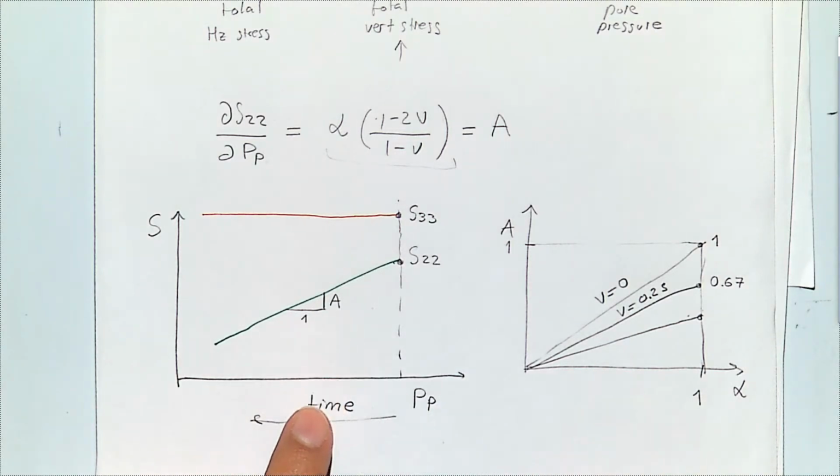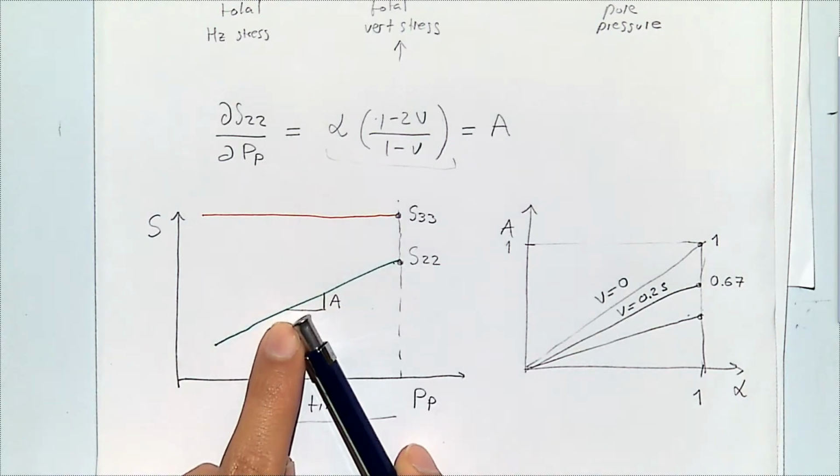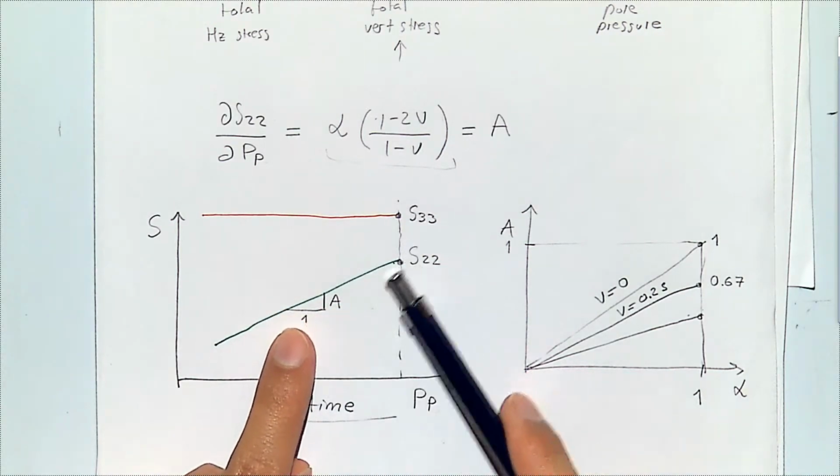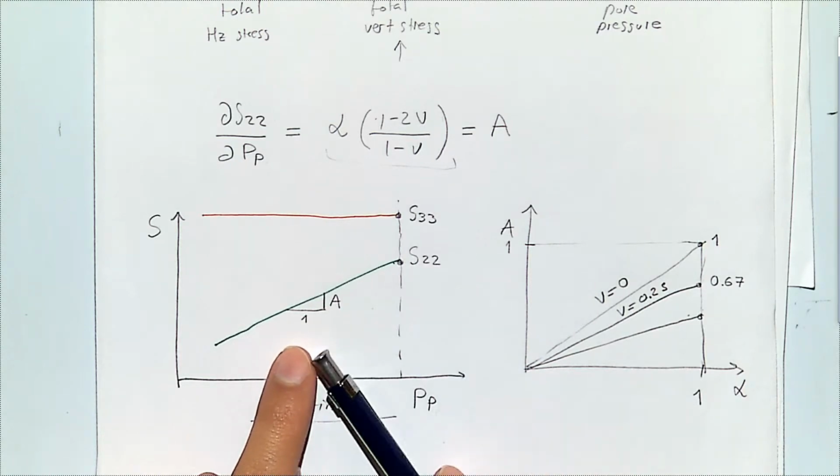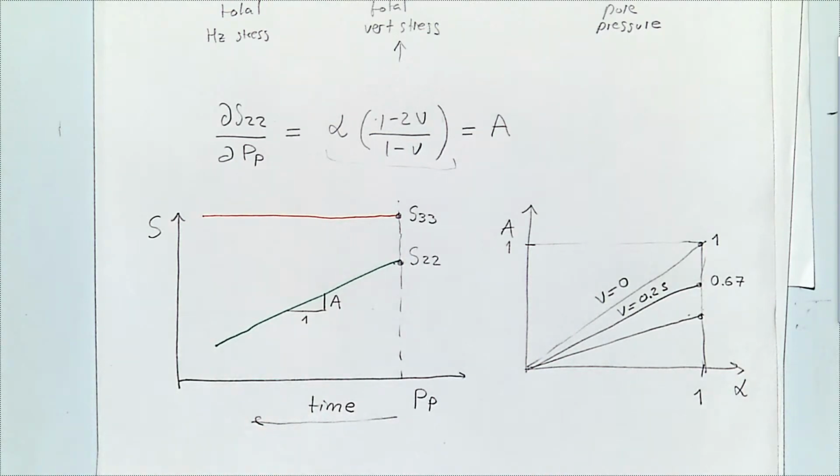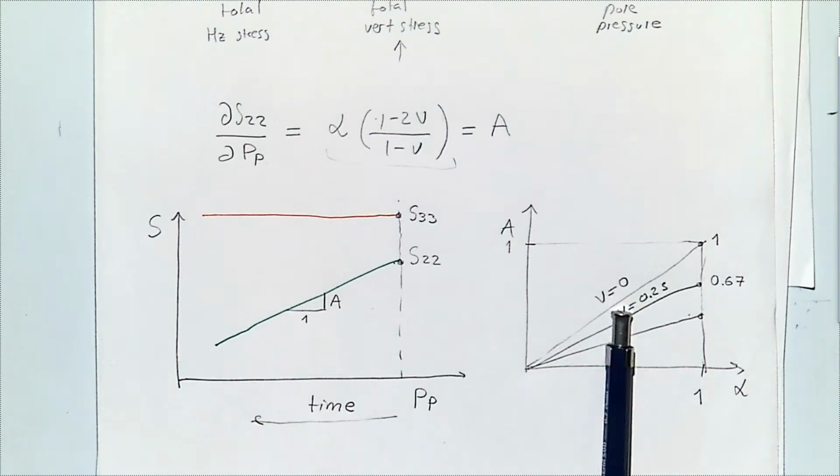Because it's not expanding into the lateral direction, and it's not relieving any stress into the lateral direction. So it's just going to go down with the rate of pore pressure. When the Poisson ratio is equal to 0, it just takes all the load in the vertical direction, and it doesn't expand in the perpendicular direction.